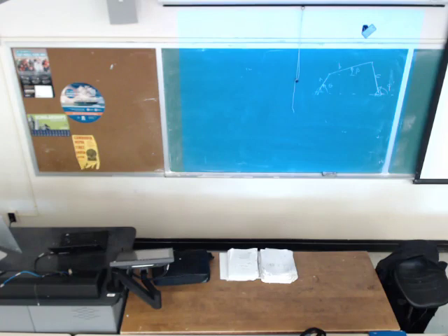In this example, we would like to design a 4-bar mechanism to generate y equals sine of x. So x represents the angle, and y should represent the sine of x. We are given a correlation between x and y, and we would like to design or size the links of the 4-bar mechanism such that it generates this desired function for us. These are the givens. The range of input motion is that x should go from 0 to 90. So here, it should start from x equal to 0 and go all the way to 90 degrees. If it goes from 0 to 90 degrees, y, which is sine of x, should go from 0, because sine of 0 is 0, to 1, because sine of 90 is 1. So it's going from 0 to 1 while x goes from 0 to 90.